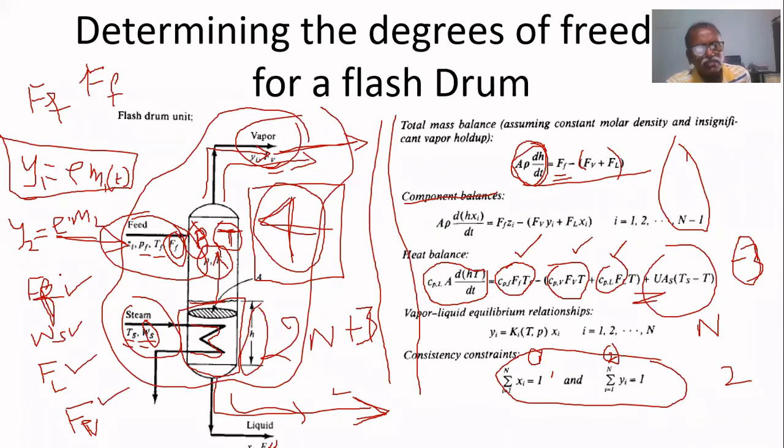Yes, very much possible, because for constant heat input, at steady state, constant heat is injected inside. If you decrease the feed flow rate, temperature will increase. If you increase the feed flow rate, temperature will decrease. Therefore, the feed flow rate can be used to control temperature also.